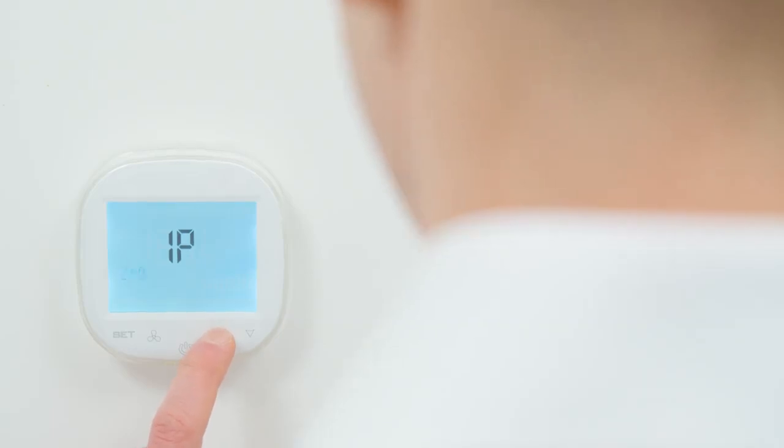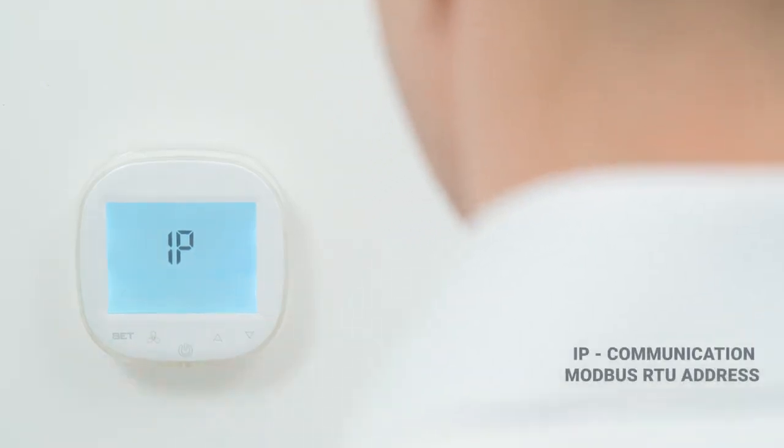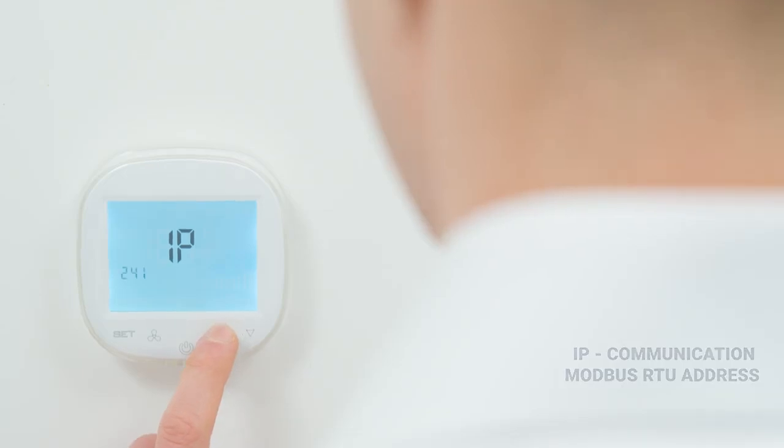Change the values of the individual functions by pressing the up and down buttons and press the set button to switch to the next function. The IP function is to change the address assigned to a building management system, BMS.